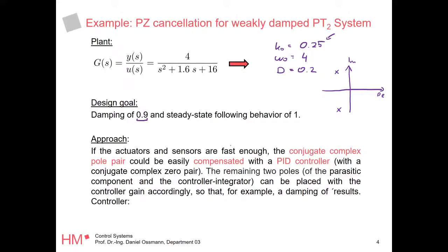Okay, you can say we have learned today that canceling poles is sometimes a good idea. So why not try canceling these two poles, right? So we're going to cancel this pole here with a PID controller, and we're going to introduce the PID controller has a pole at 0. We're going to introduce that. And a PID controller is kind of non-causal, so we're going to use R of S, S, right? PI, the I of the integrator here.